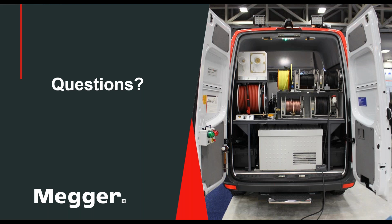All right, thank you. So, Sergio, is the elbow jumper shielded or does it have a wire ground? Let's see. So the elbow itself has an unshielded portion on the lead just before the elbow boot itself. And if you have the high voltage lead, there will actually be a small lightning bolt laminated picture on that section so that you know in between here and here is unshielded. And then the ground itself is on the high voltage return as well. So it's all intertwined together. Hope that answers that question.